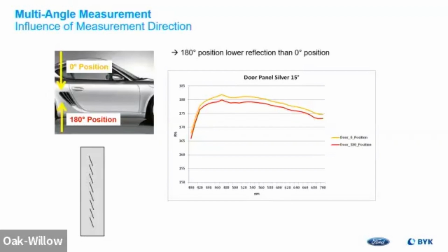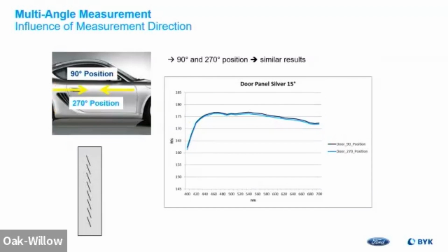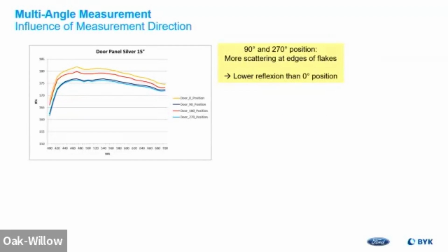But on the vertical surfaces, if I spin this instrument, I'm going to get a difference between my two measurements, and it's quite significant. And if I turn it 90 degrees or 180 or 270 degrees, I'm going to get the same type of data, but compared to the other two, it's going to be very different. So we've had customers call and say, there's huge variation between our first and second shifts. And then we'll go actually to the customer and they're measuring one way during the day and a different way at night. And it causes lots of problems.